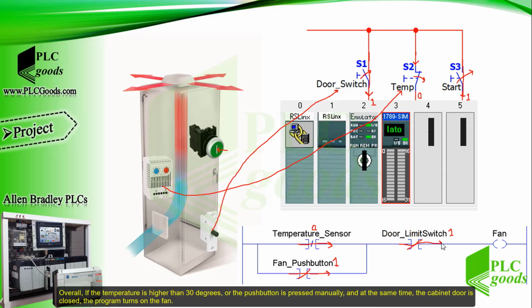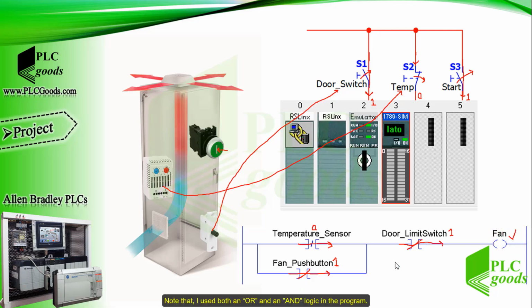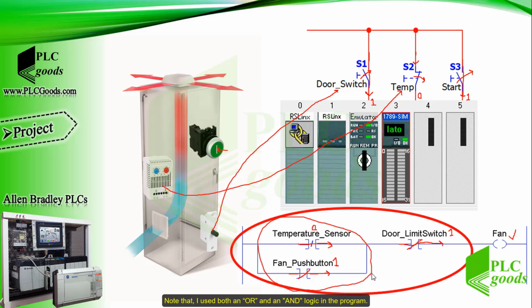Overall, if the temperature is higher than 30 degrees or the push button is pressed manually, and at the same time the cabinet door is closed, the program turns on the fan. Note that I used both an OR and an AND logic in the program.